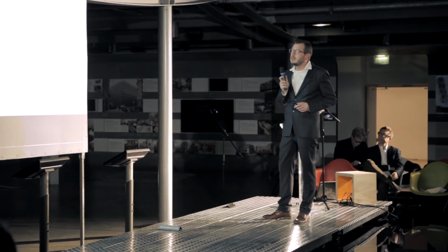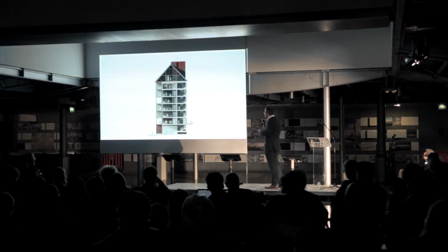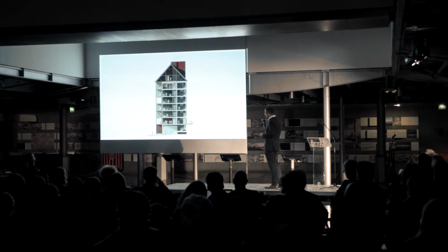Section of the building. The foundation is totally an ancient stack of natural stones put together. The bottom of the building is ventilated. It's just a buffer zone preventing moisture and everything from rising up into the building. The frame is wood. The corridor spaces are covered and fire protected by clay boards, a clay and natural textile combination. And the attic is another buffer zone,